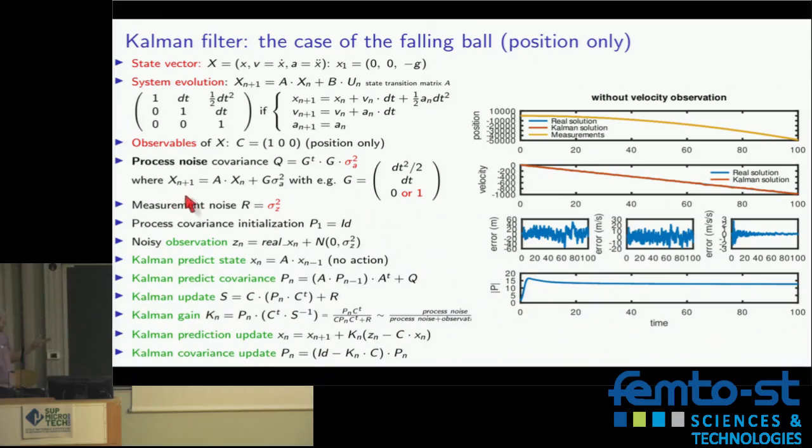And so Kalman filtering asks you to give a model noise. Gonzalo confirmed, because every website gives a different formula for the process noise, that this is where you put the black magic. You estimate how poor your model is, or how much you allow the Kalman filter to leave the model when it says the observation is better than the model.